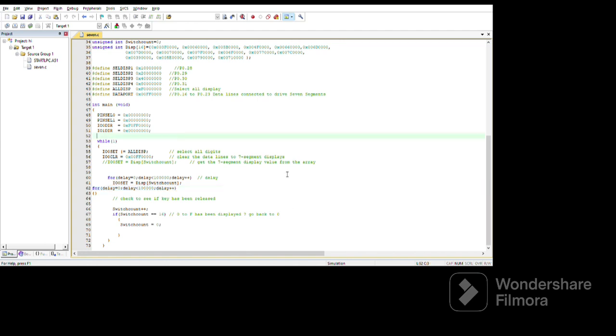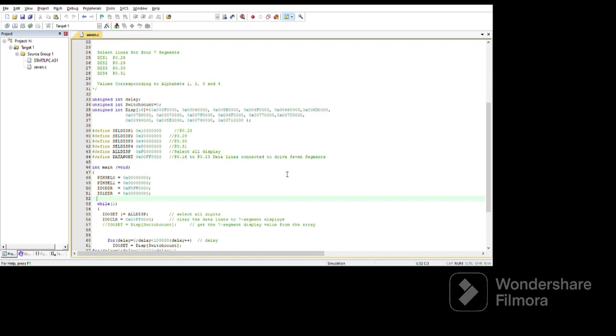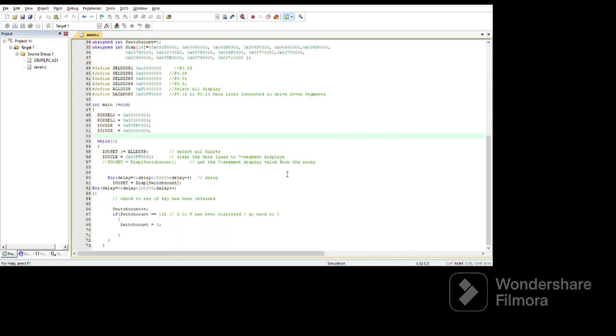Now you all can pause the video and check for the code. Now as we have written the code, let's upload it to the LPC2148 microcontroller kit and see it in action. Once we have the code uploaded, we should be able to see the counter value being displayed on the 7 segment LED display, cycling through each digit smoothly. If the counter's values are flickering or something, we can increase the delay and check again. Okay, so now I'll be checking it by burning the code onto the LPC2148 kit.